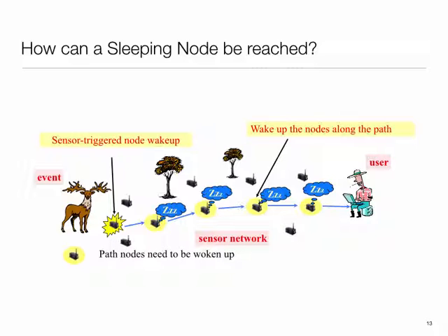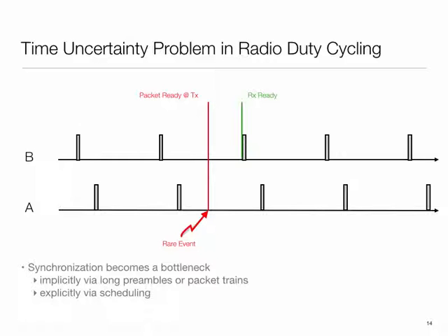So the alternative is to fake this via protocol. Let's try to do a notional design. Imagine I have radios at either end of a link, and these radios are waking up periodically. So node A and B: A wakes up periodically to listen if there is a message for it.